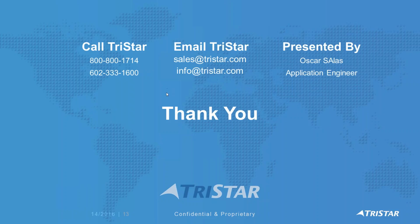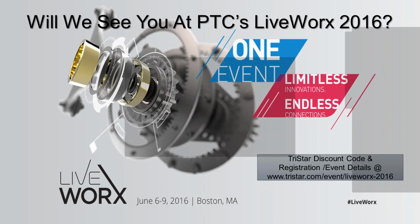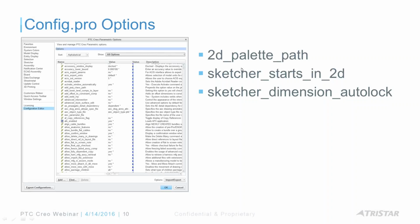The Config.pro to, let me go back over here. So from Colin, the Config.pro to add tabs to the Sketcher palette. So I'll go back here on the PowerPoint to show you guys those Config.pro options. So that's going to be 2D_palette_path. Okay, so that's the one that will allow you to add multiple tabs to your Config.pro. So you know, those are right now.